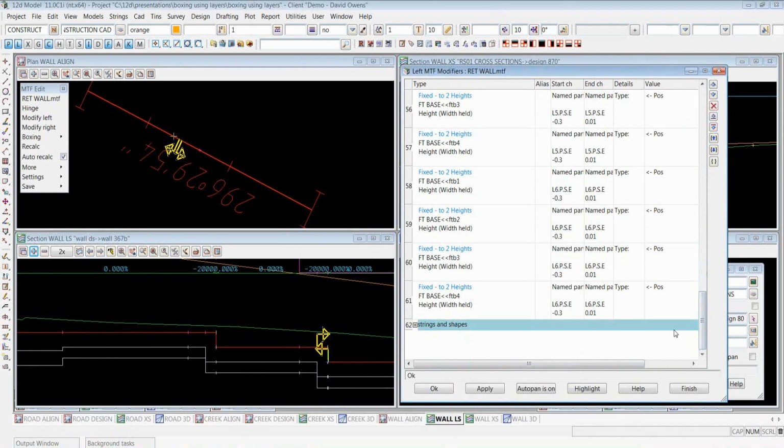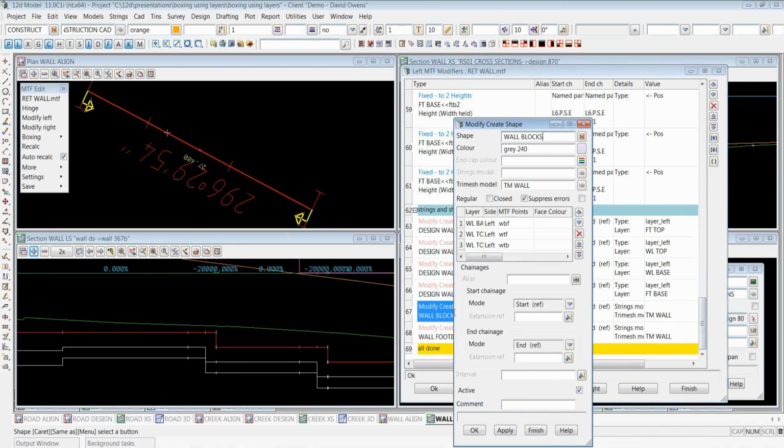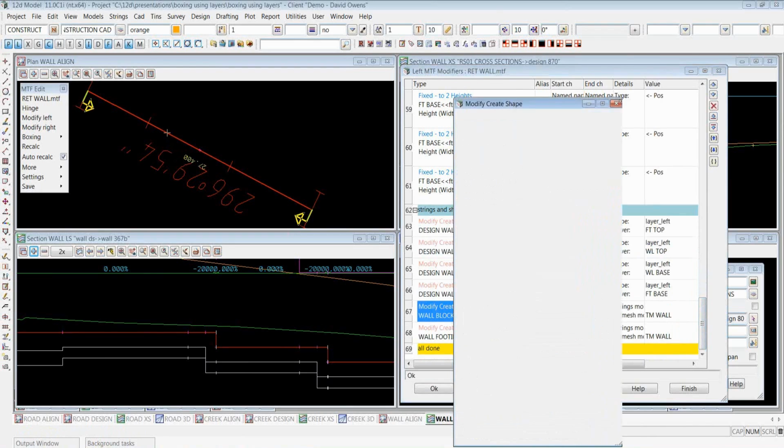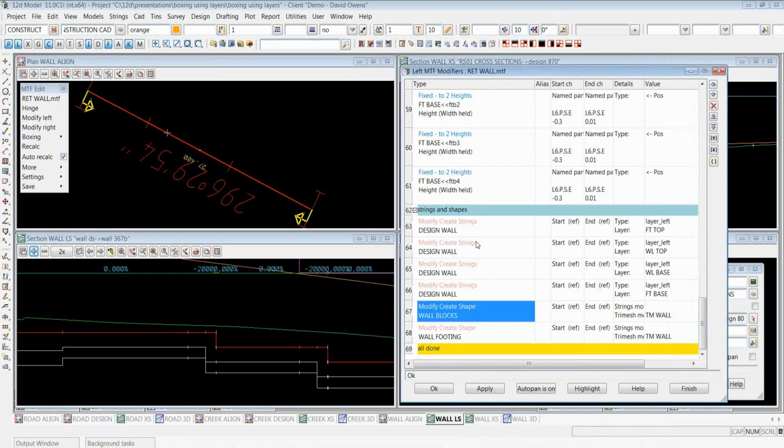Okay. So plenty of them, it all just depends on how many steps you've got in the footing, of course. And at the end of the day, it's just a case of going through and joining the dots. So all those points that were created, the wall back, the wall top, all that kind of thing, all the different layers. I created a lot of different layers in this situation because I had a lot of things happening in different places. It just made it a lot easier to get my head around. That was the top of the wall, the base of the wall, top of the footing, base of the footing, all those kinds of things, all broken up into different layers, just to make it simpler on myself, to be honest.